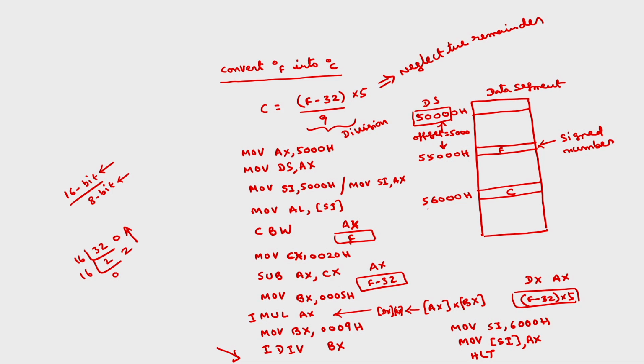So we will discuss the next program. Suppose I want to compute in the CX register, I want to store say 5 into AL contents minus some 6 into BH contents plus contents of BH by 8. Basically this is multiplication. Okay.